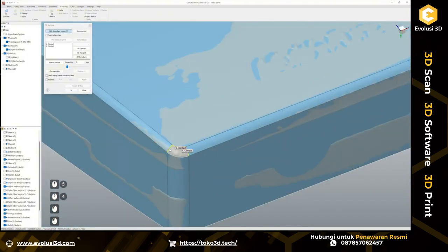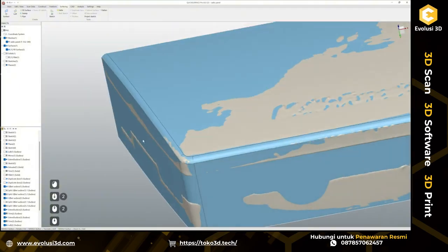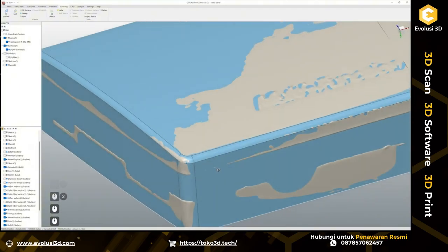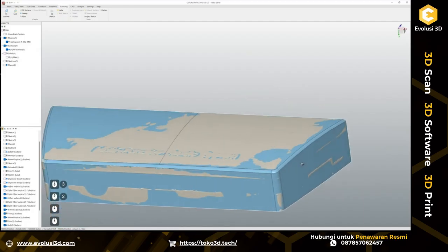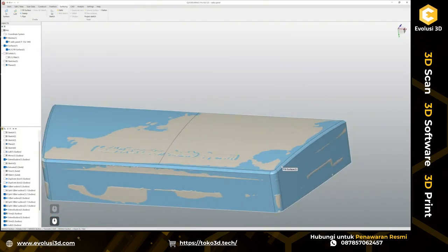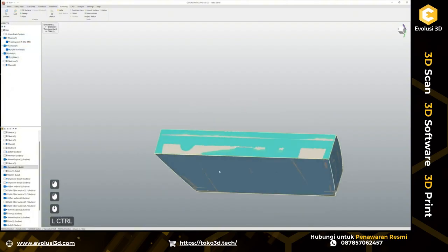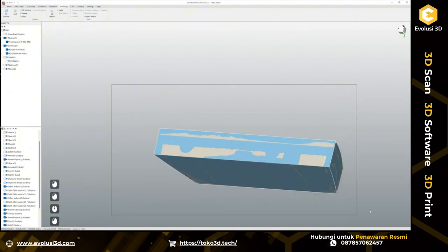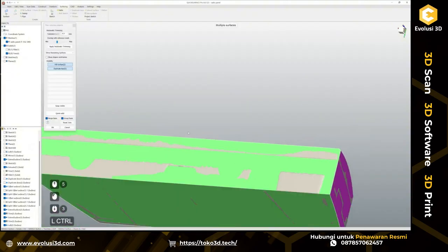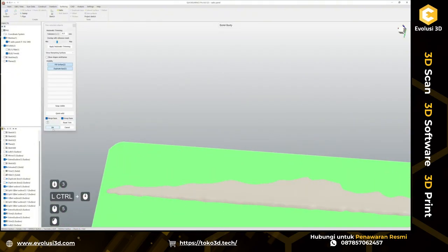And repeat the same on this corner. Tangent, tangent, tangent, and contact. Great. So now we have these nice edge lines. And I like this much more. Actually, this reminds me of what you normally get when you add a fillet and would see the proper surface patch edge lines. Okay, so again, hide the solid. Let's duplicate those two surfaces. Trim all this into one single solid. Okay, good.